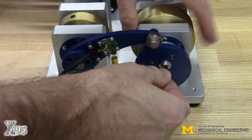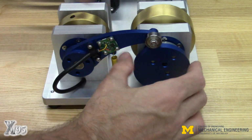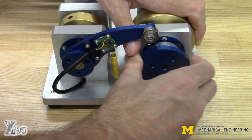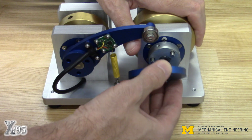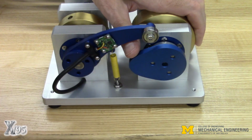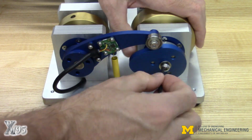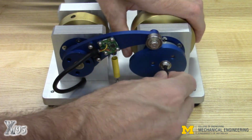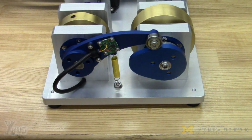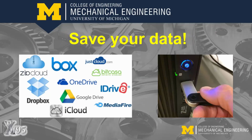To change the cam, loosen the center screw with the provided Allen wrench and gently ease the cam off the dowel pins. Orient the holes of the new cam with the dowel pins and slide forward against the hub. Then reinstall the 1/4-20 screw and gently snug it. Don't over-tighten. Please be sure to save your data before you leave the lab today.